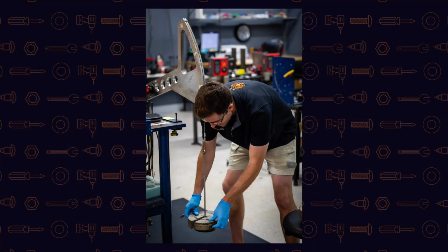And this is done through torque calibration. In this example here, you can see we have an analyzer that is hooked to a segment arm. And this arm can have different lengths to it. So we may be measuring, say, a 2 foot arm, and we are then applying a load to the sensor and allowing the system to calibrate the actual resistance that we are reading from the strain gauge to the analyzer.